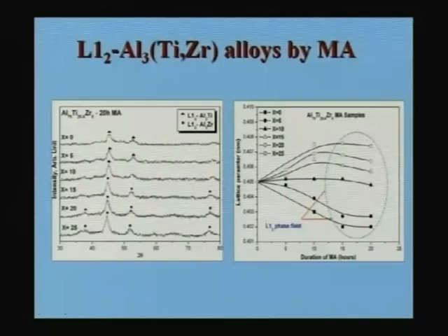I told you that in mechanical alloying, the phases that come out are always those with lower interfacial energies, and high symmetry structures such as the cubic structures. High symmetry structures always have much lower interfacial energies. So the cubic structure can form much more easily.